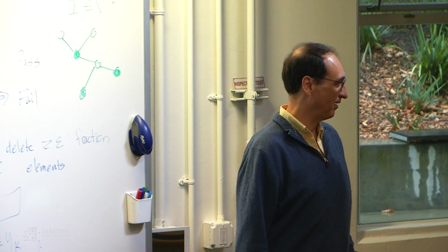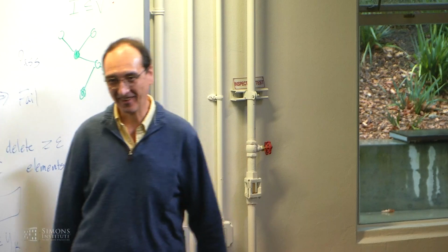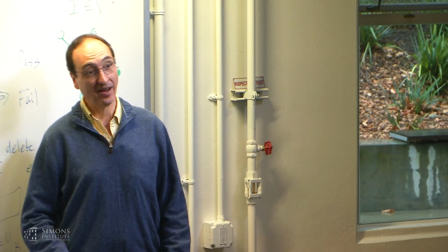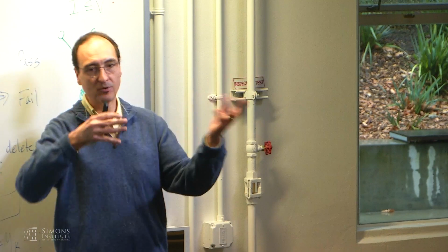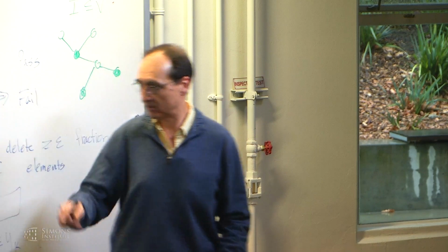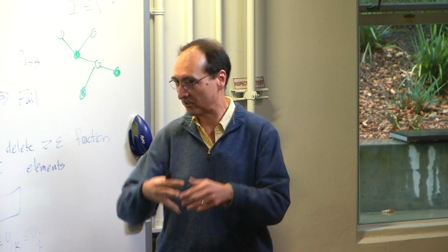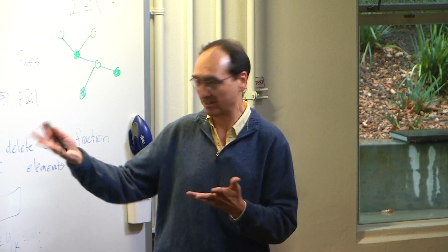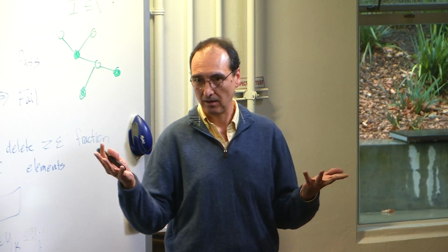So if I can convert my problem into this form, I just have to call a function in MATLAB or Python and I will get the gains. And this is what we do. It's like, you give me a room, and I say, okay, here's the dynamics of this room. I now have to figure out what the state, the temperatures, et cetera, are, and figure out how much to turn the heating on. So I give you A, I give you B, I give you some cost functions to say how much power costs, how much you're willing to tolerate the differences in temperature. That's the Q and the R matrix. Give me the optimal controller that minimizes that quadratic cost.